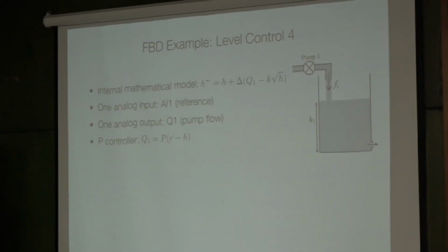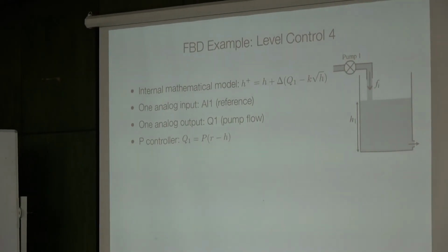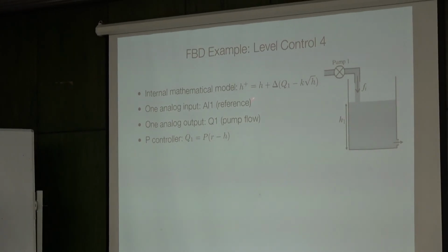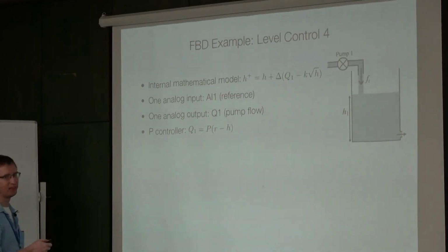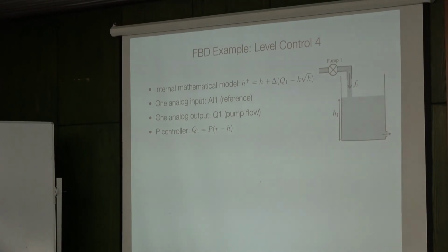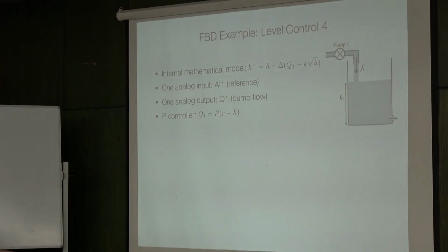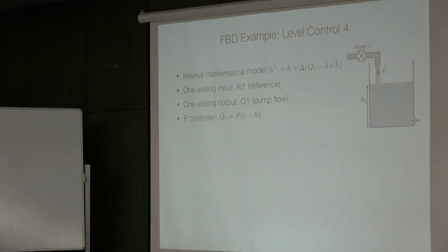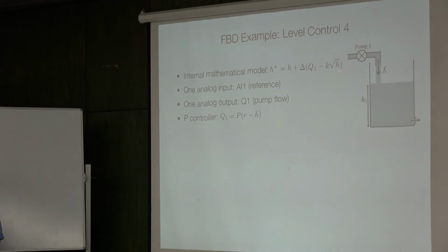Let's do just proportional control. We will consider that again we have this measurement, but this time the measurement will not come from the outside world. Since we are in a complete simulation, we will also include a simulation model directly onto the PLC. So I will just be including a nonlinear simulation model with one state. I mean, the accumulation is equal to the difference between the inflow and the outflow. And we would like to regulate the voltage to the pump by a simple P controller, right?